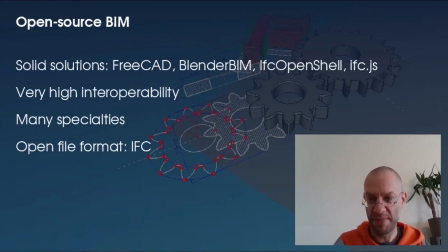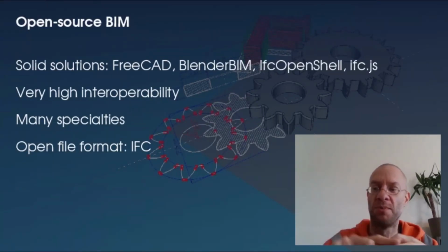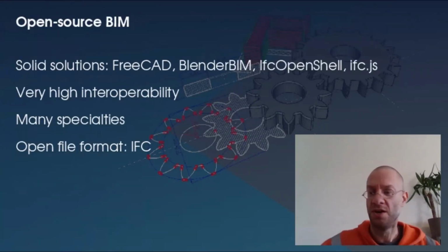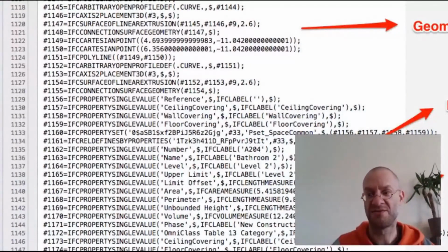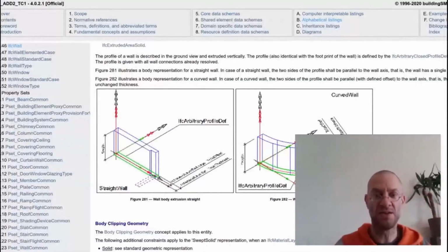You have many specialties. You have software for modeling, for analyzing, for producing, all kinds of byproducts you need around. And there is one big file format used everywhere there, which is the IFC file format. The IFC file format is an open standard. It's managed by a consortium. It's extremely well documented. All the specification of what's inside that file format, how it must be formatted, is open sourced. It's well explained how you must compose your file.